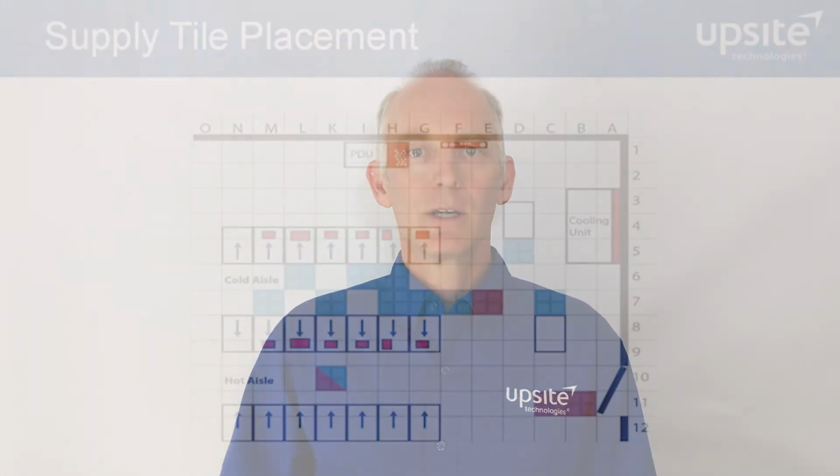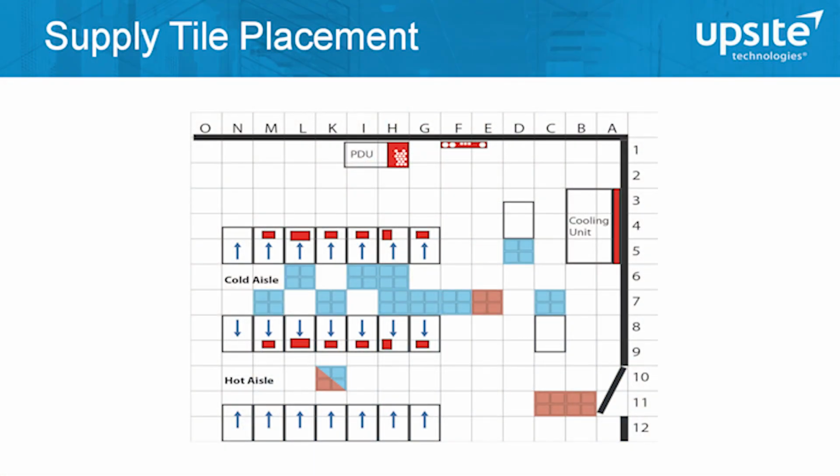Let's now talk about placement of perforated tiles, supply tiles. Obviously, the only place that they should be is where the air coming out of them is able to be consumed by IT equipment adjacent to them. As you can see in this diagram, this plan view looking at the floor plan of a data center, there are blue and red supply tiles here. Obviously the red ones are not good. Those should not be there.